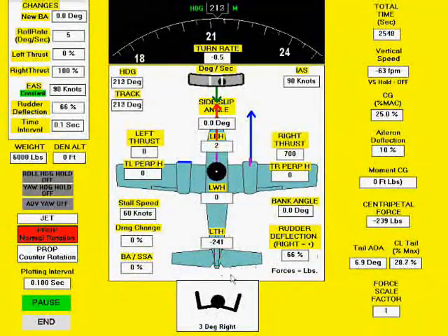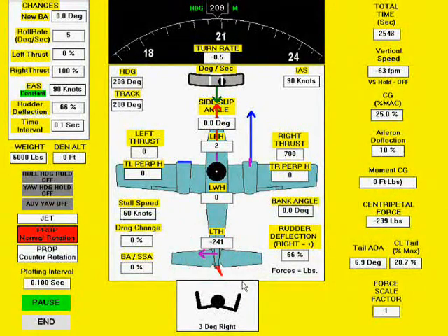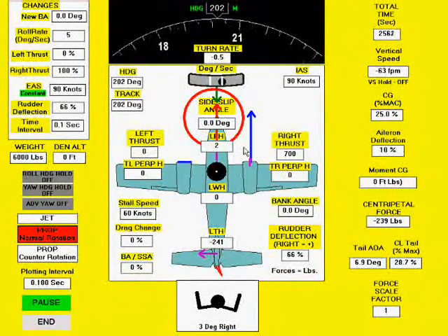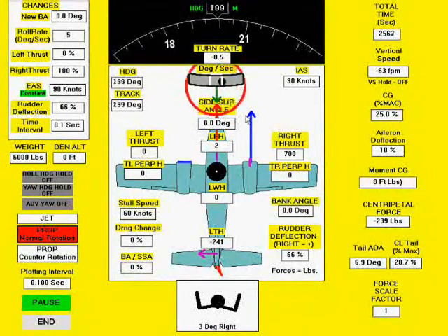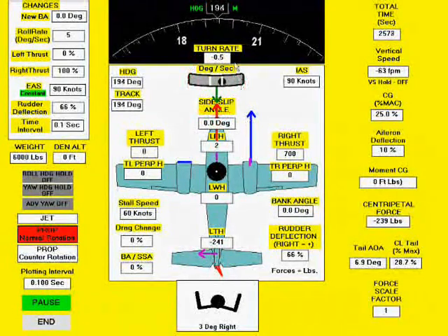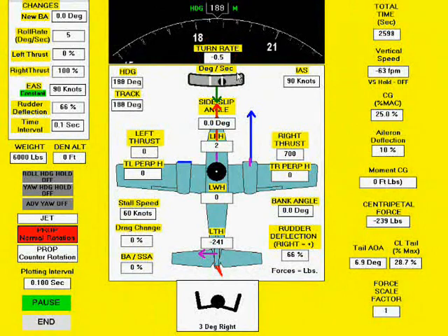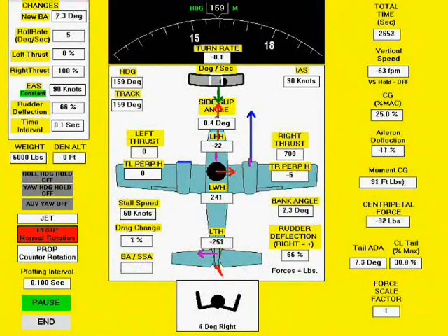But the vertical tail lift is providing the centripetal force to cause a turn. We eliminate most of the centripetal force with a slight bank toward the operating engine. Horizontal wing lift now cancels the vertical tail lift. With slightly more than 2-degree bank angle toward the operating engine, we are able to maintain a 0 side slip angle. Note the right ball deflection.